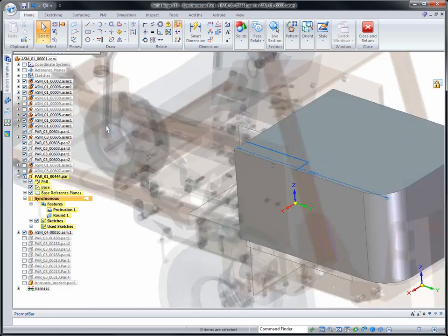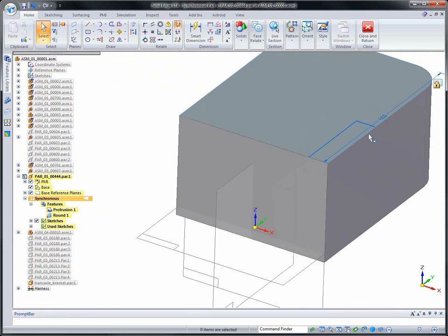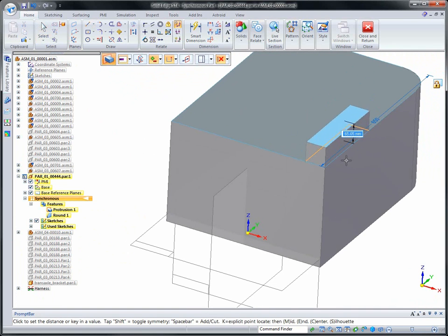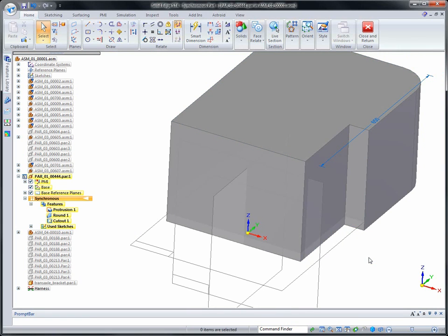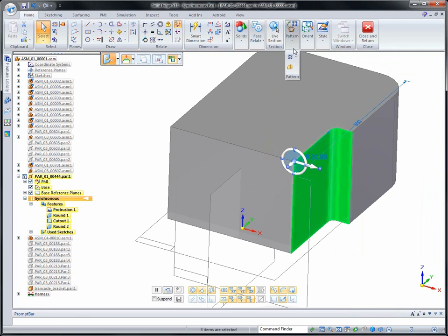When selected, closed regions display a handle, and a quick grab and go turns them into a 3D feature. Pulling regions adds geometry, and pushing it removes material. With fewer commands to learn, new users adopt Solid Edge faster, and experienced users design more efficiently. Next, we'll mirror this to the opposite side.